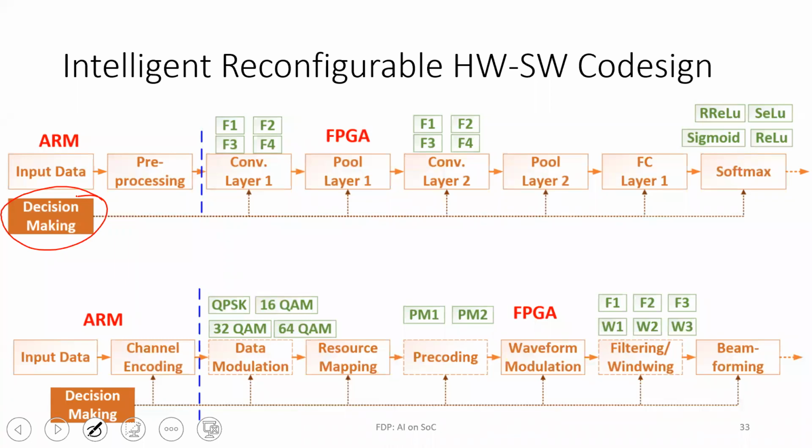Very good question. That's why I was giving the example of 4G to 5G. If you are going to develop your product in millions of volumes, today there is no alternative to the ASIC. So whatever reconfigurability you need has to be done at the processor level or the GPU level. The ASIC part will be fixed. But the FPGAs are used for prototyping in the ASIC industry itself.